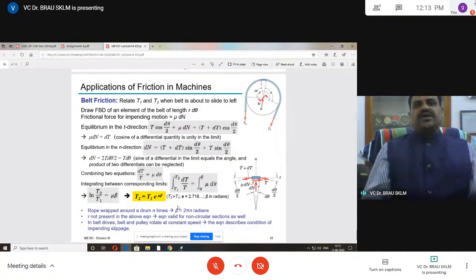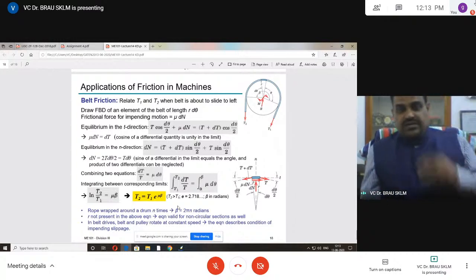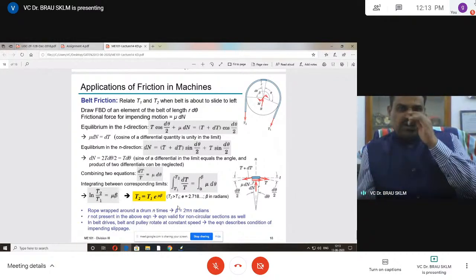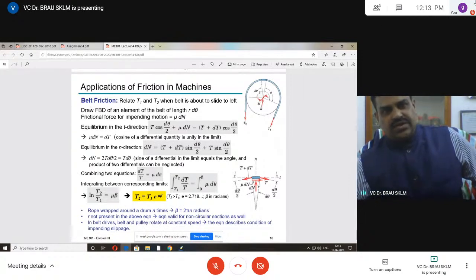See, these are the different mechanical engineering applications that we will come across, even in civil engineering, when we are discussing beams, plates, those are all rough surfaces, bars, trusses, etc. Generally you neglect the friction, but if you are considering friction at the joints, pin joints, hinge joint, roller joint, that is where the two rubbing surfaces come in, and you can use the horizontal forces and the vertical forces and try to do the analysis.